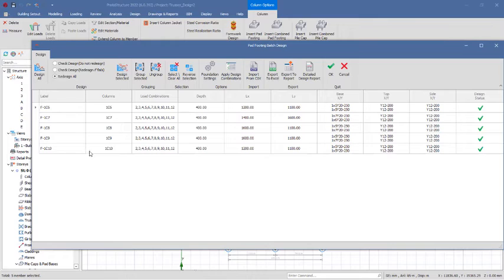Okay, so the same thing is applicable to these other directions. Get all selected, right click right there, and select insert pad footings options. So we are designing all. Alright, just like this. As I said earlier, we design all. Okay, you can forget about grouping and then you design all of this. Okay, so you select design all these options. Alright, so we did not use group selected.